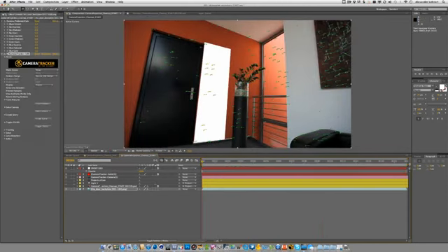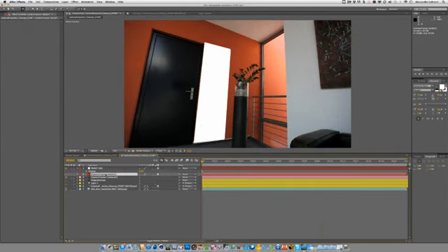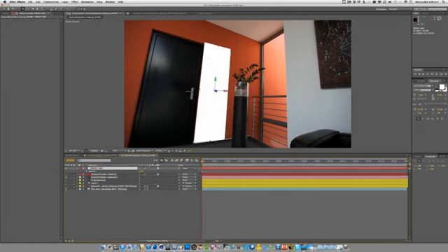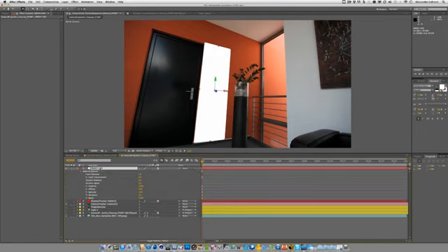Alright, so I just make this invisible, as we don't need that anymore. That was just for setting up the scene. Okay, so next step we need to do is go and change the material settings on our proxy geometry. So for that I double hit A and then the material options pop up.